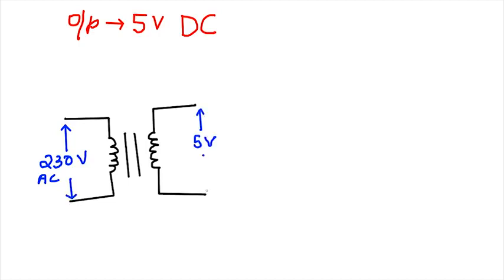However, I shall use a transformer of 12 volts as output voltage. Why? Well, I'll get to this point later. So a step-down transformer with 12 volt rating is what we will be using right now. If you have any previous experience in electronics, you may know a transformer's input and output are both AC voltages. So next step is to convert this 12 volt AC signal to DC.